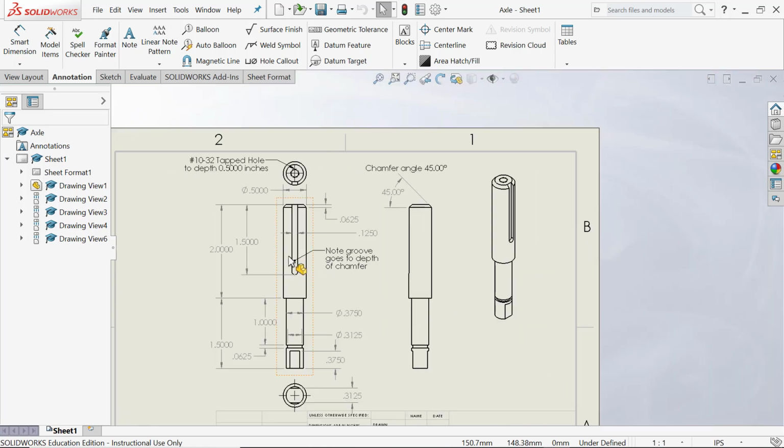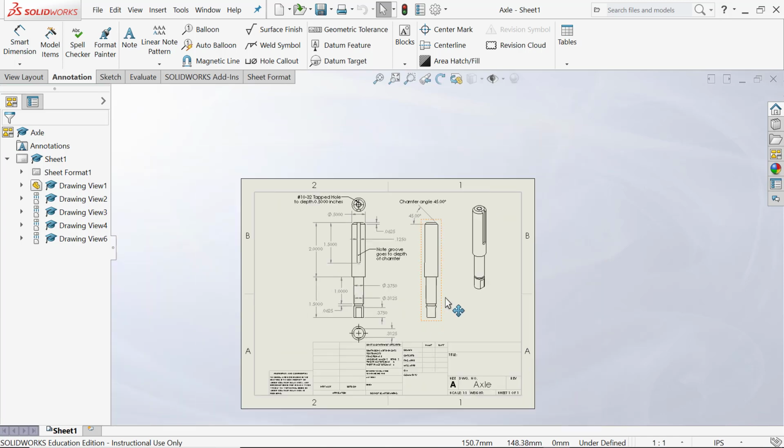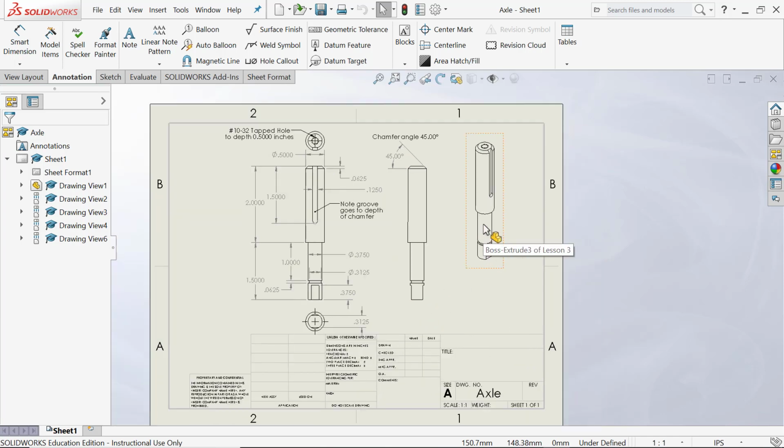And the extruded cut will just be blind by 1.5. Does that make sense if you look at the part? And then we'll fill it at the bottom there. The lower cylinder could be created by drawing on the bottom of the top cylinder a circle whose center is centered on the origin. It'll just be a smaller diameter. It'll be 0.375 instead of 0.5 like the first one. Right? Does that make sense?